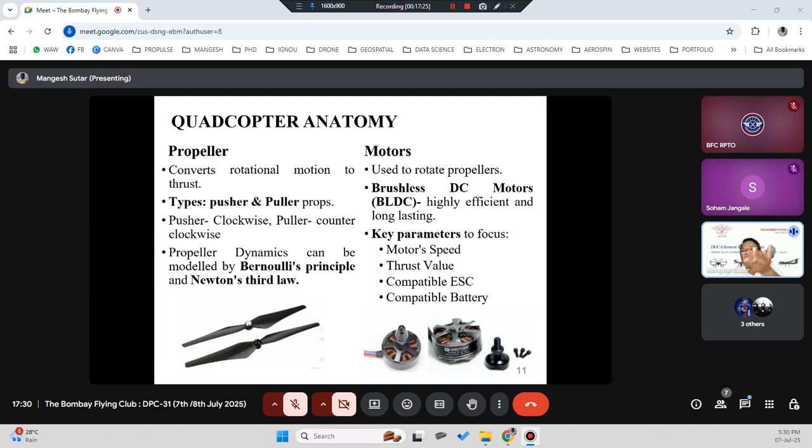So when I connect 4 motors, 4 times 10 gives me the capacity to take a weight of 40 kg. That is more important. Once I know my drone is capable of picking 40 kg, I decide what ESC is compatible, what propeller is used, and what battery is required based on my endurance capacity. All that is secondary. So when designing a drone, the first thing I decide is the motor and the thrust value I am getting. Clear?